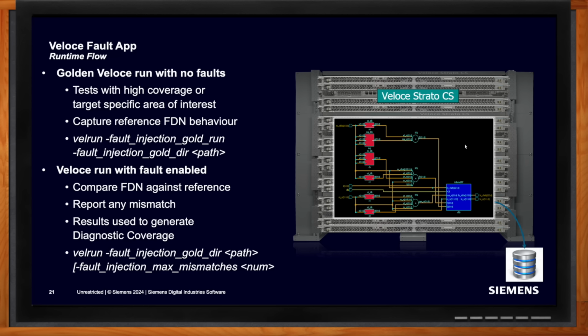coverage at this point. Again, all of those runs go into the database, but it is the safety scope tool that now will analyze that database across all the different sessions, across all the different execution engines, the IPs, the blocks, and so on and so forth, and generate the final ASIL coverage metric.